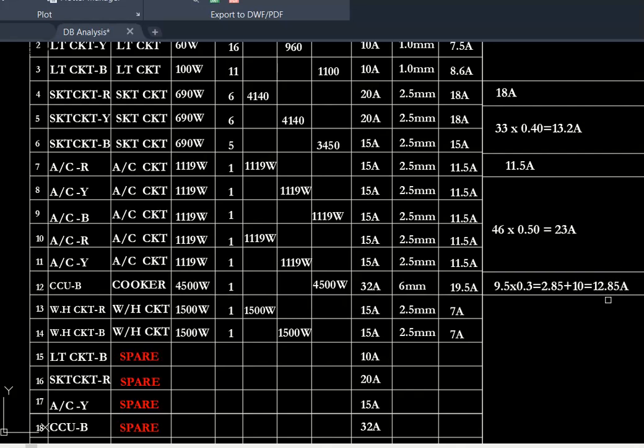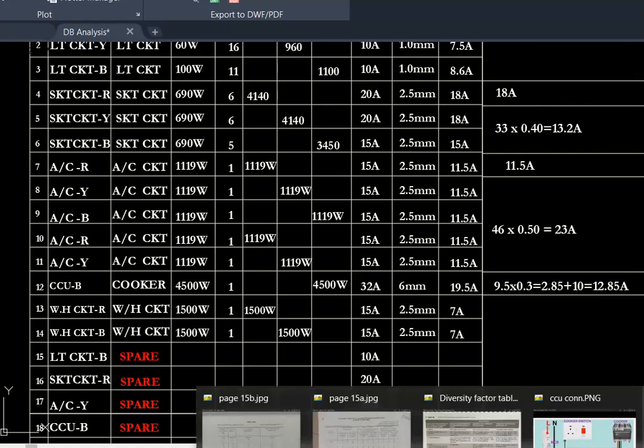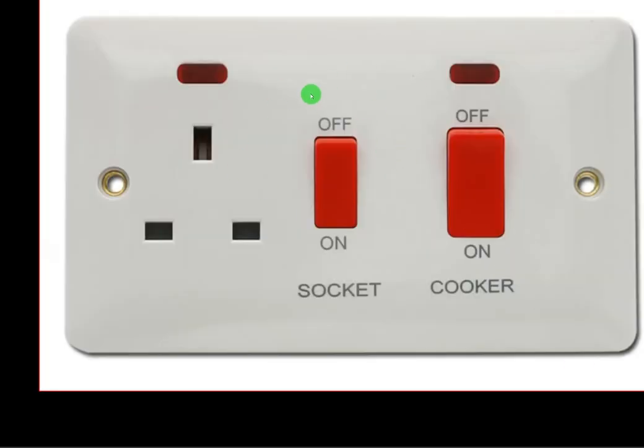Okay, all right. So let me show you the cooker, because some people misuse the cooker. Now let's talk about the cooker. This is not how to use it, because that is the wrong approach that people normally adopt. They will buy the cooker and buy a 13 amp plug and attach it here. In less than a few months, you see that this place will go bad, will go burnt. And once this place goes burnt, the entire system is bad. So you have to change the entire panel.